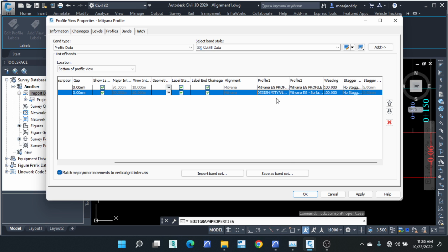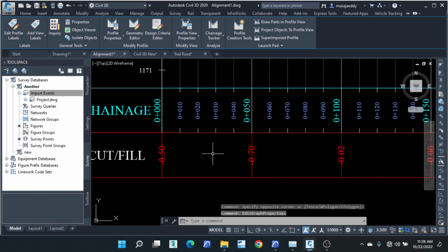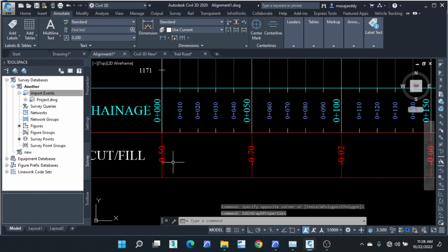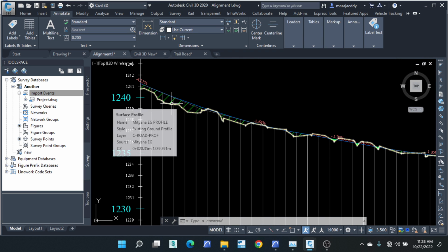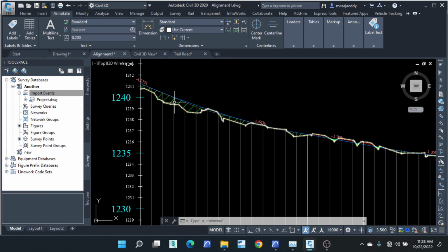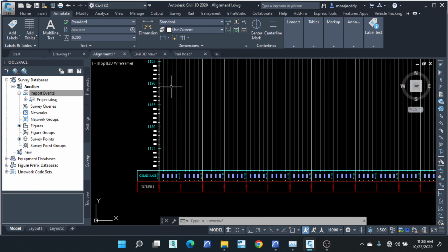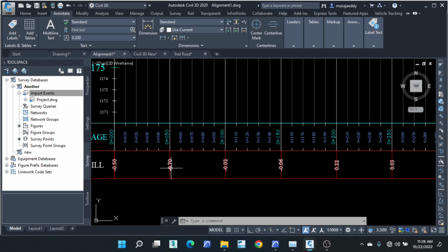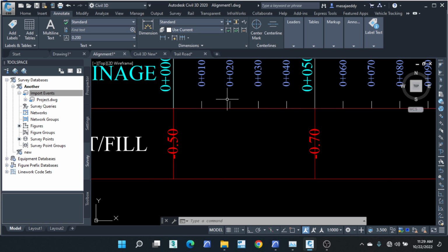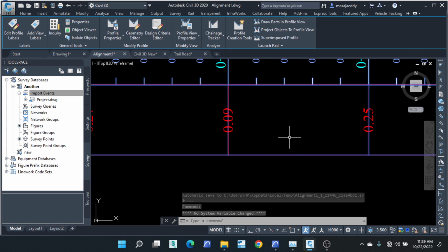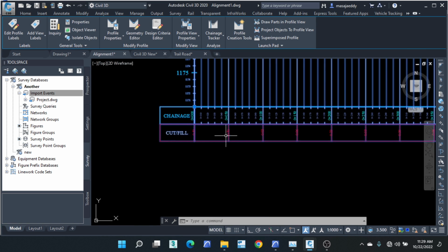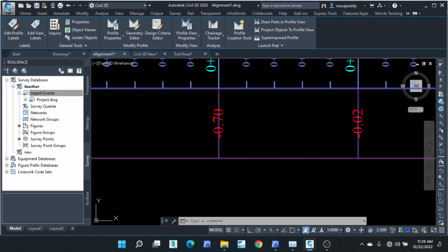So that is okay. Once I click OK, the values that we are having here, which are negative, are for cut. That means that if it's a negative value, it's a fill value, right? Which is here. We are filling instead. The equation I've used is for cut, it's not for fill. So since the equation I've used is for cut, the cut values are supposed to be positive, the fill values are supposed to be negative. As you can see, I have some positive values, and I equally have some negative values. Those vary accordingly. So we are going to keep editing.